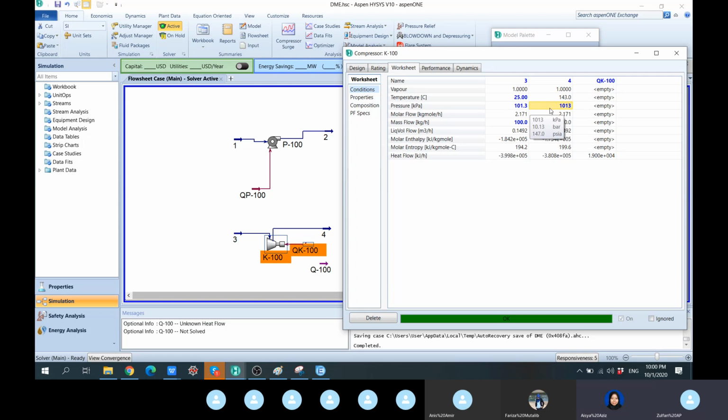That is because there is a mechanical constraint on the seal or material that they use within the compressor, and that's why they tend to use a compression ratio of 2, 3, or 4 even, depending on the gas compositions.